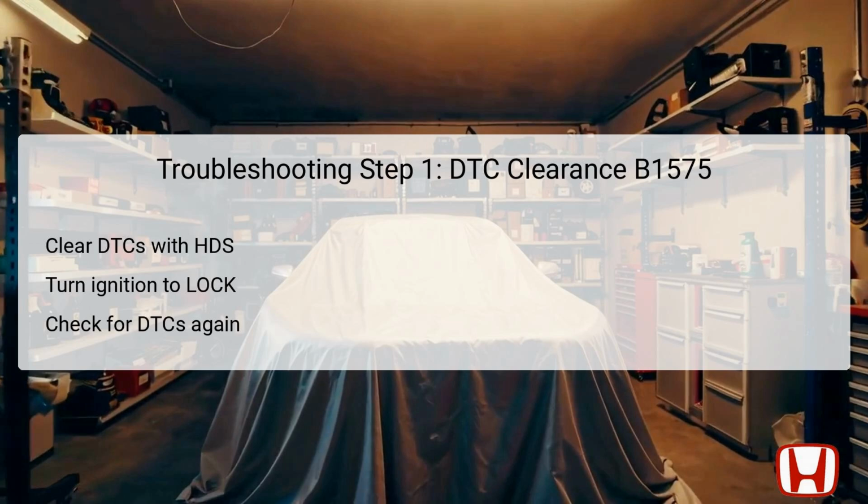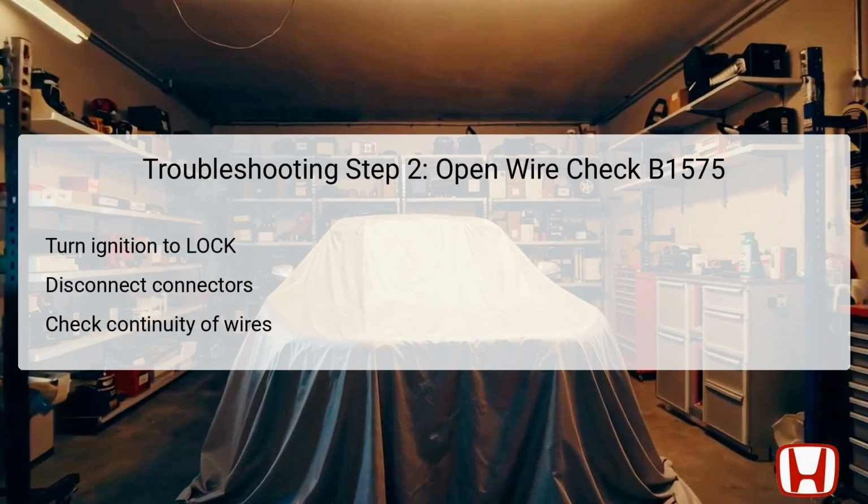Once the ignition is on, check the DTCs again with the HDS. If DTC B1575 reappears, proceed to the next step in the diagnostic process. If it does not appear, it may indicate an intermittent failure, suggesting that the system is operating normally at that time. In step 2, focus on checking for open wires in the critical circuits of the automatic lighting system.